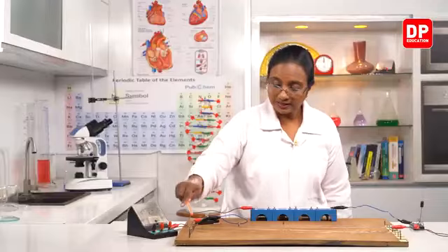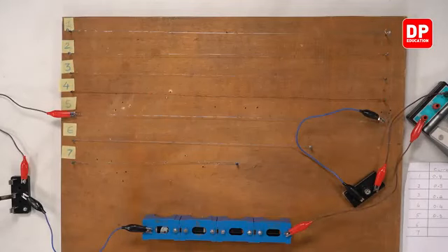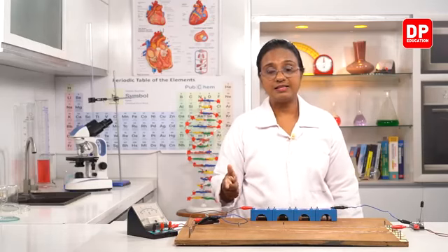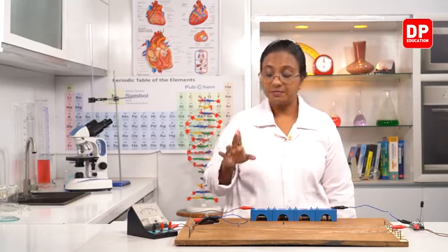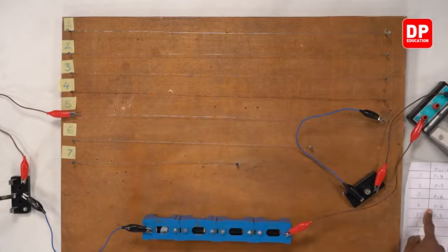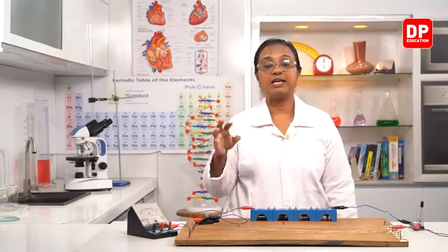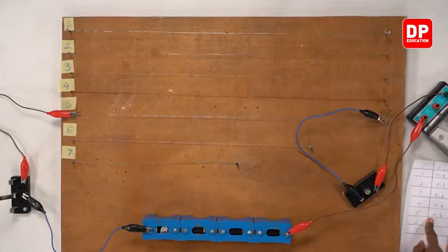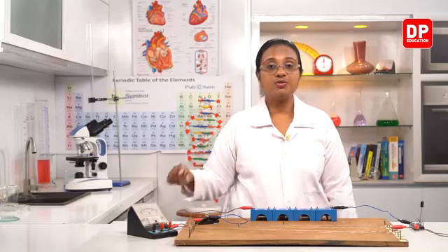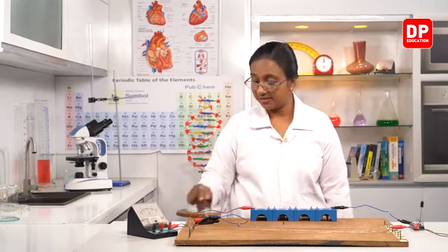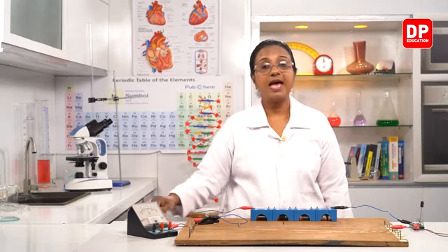Now if you look at the three conductors, 3, 4 and 5, nichrome, copper and iron. You can see the cross-sectional area is the same, length is the same. Only thing that is different is the material. Through copper, the brightness was the highest and 0.4 amperes. Highest current flows through copper. That means the resistance of copper is the lowest compared to the three. So after copper, if you look at it, it is iron, 0.3 amperes. So that has a little more resistance, and nichrome has the highest resistance by 0.2 amperes, and the brightness was the least.